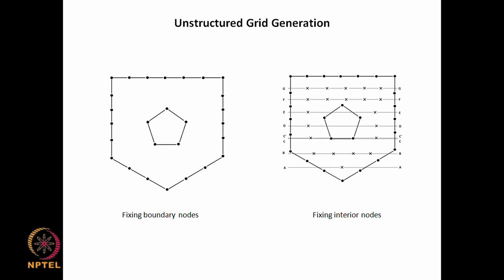You can also extend this logic to 3D. So, in that sense, nodalization, which is the task of putting points inside the computational domain, so that all points are inside the computational domain and they are spread throughout the computational domain, requires some estimation of the distance between the points that you would like to have.